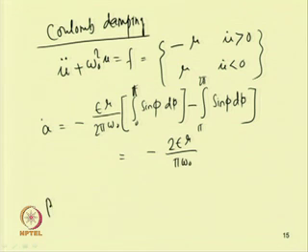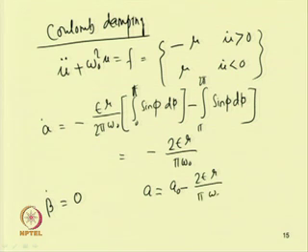Similarly, we can find the beta dot equation. Beta dot equal to 0, like in the previous case. So, the solution becomes a dot equal to this. Integrating this, a becomes a 0 minus 2 epsilon mu by pi omega 0 into t, and beta equal to beta 0. So, one can plot this function. For Coulomb damping, one can observe the solution to be in this form.